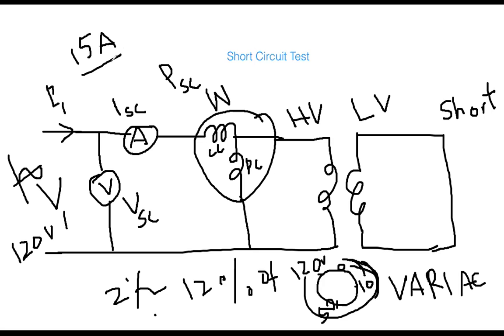Once you reach it, you disconnect and don't apply the voltage. Your test is done. It is very simple; in 1 or 2 minutes you can do this test. You just have to be careful that the ammeter does not exceed the rated value.